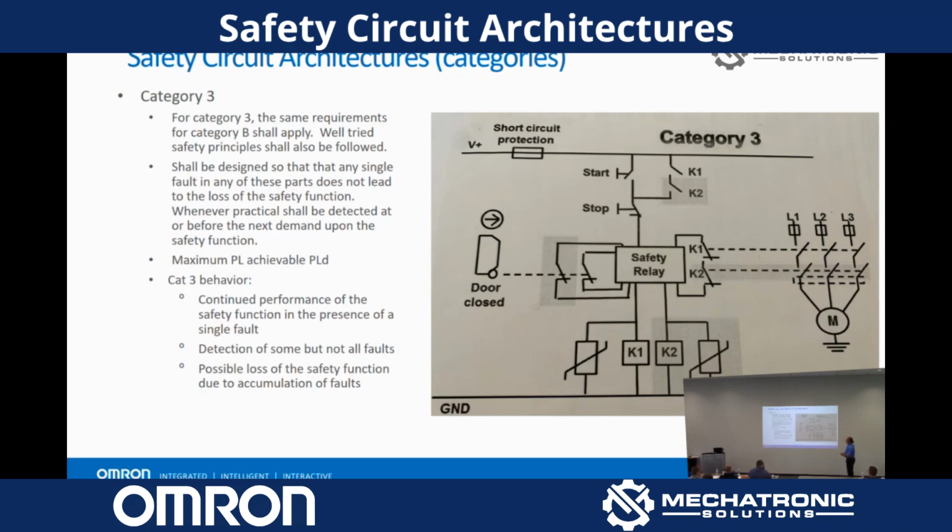So as far as resetting goes, if there's ever anything that you can pass through, you need to have a physical reset happen. This could be an auto reset, where it's like a guard door where you're opening it, reaching in, and closing it. The system would need a start signal at minimum. But yes, a reset is an important piece and most often required. This example doesn't have the reset. It's just start or stop. So you're exactly right. This is an auto reset, basically.